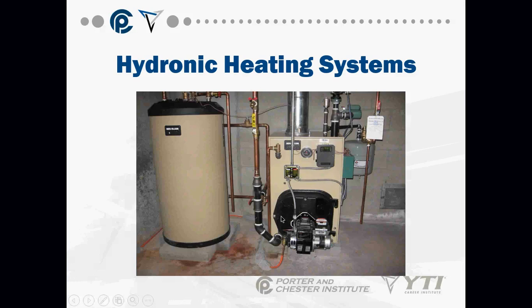All right. Here's your combustion chamber. These are actually really nice boilers right here. You take off this bolt right here. This guy actually swings right open, and you can see right inside the combustion chamber. But all up in this area here, all of this tan area, this will actually get filled up with water. Okay, and when that does, it will start to fill up the rest of the boiler. So when it calls for heat, your circulators, zone valves are all open to start heating the space.